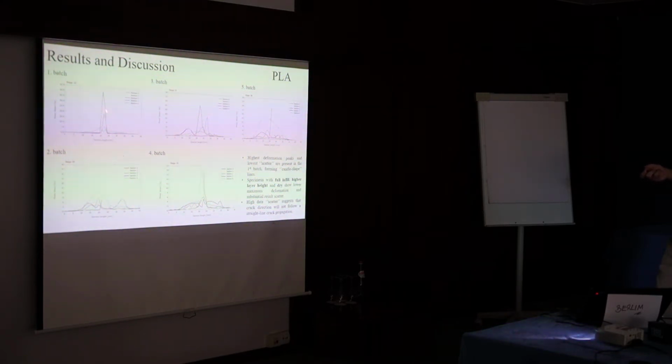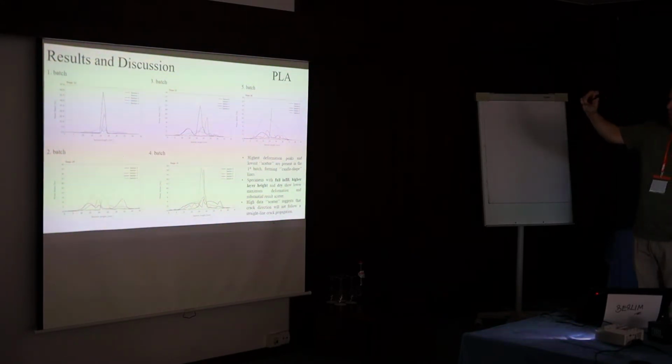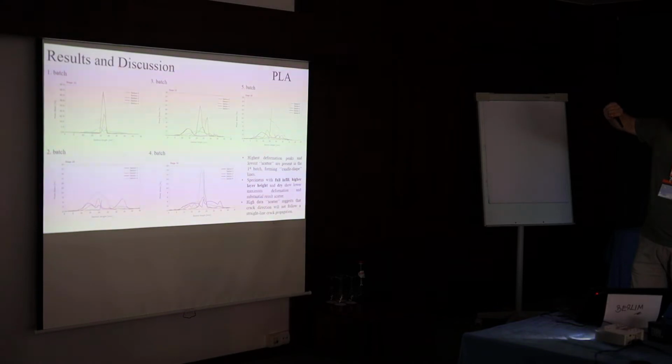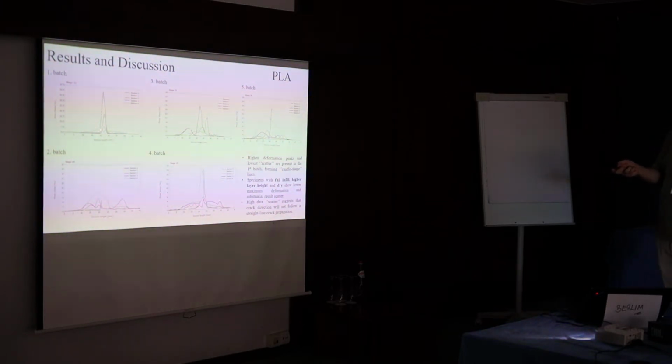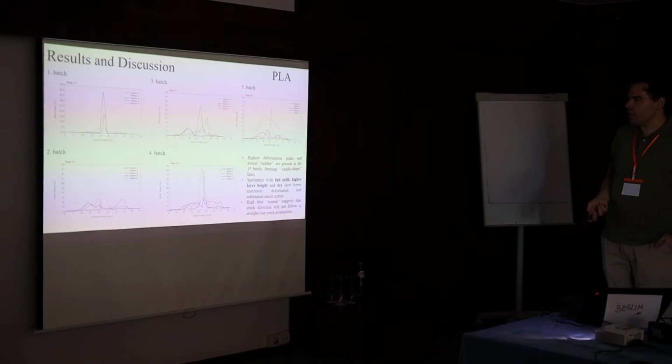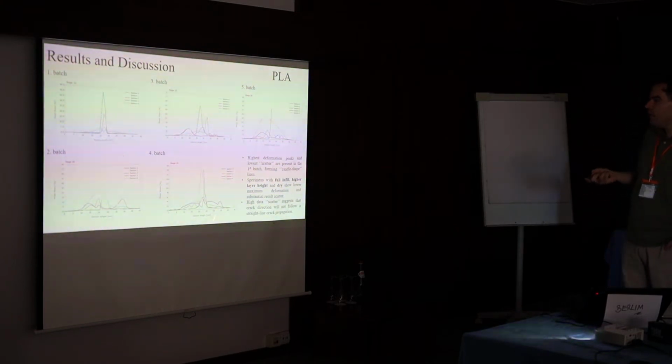Here it shows that on the middle side, where the notch and the pre-crack are, and where the crack should follow a straight line, we have the highest deformation values, and not on the left side or the right-hand side, where we have hardly any deformation. So probably this specimen will have crack propagation in a straight line, forward from the pre-crack to the imminent failure on the ligament.